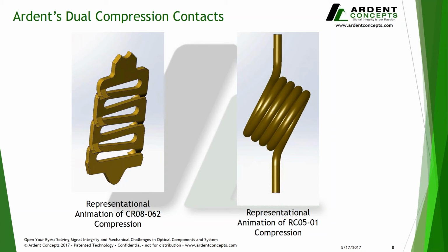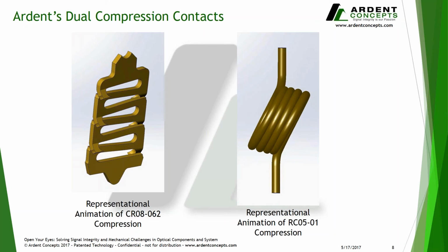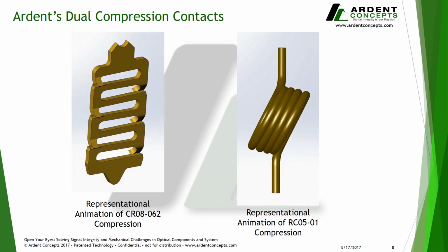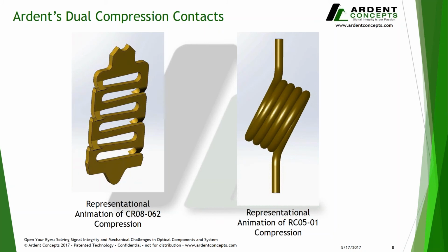You can see between the two contacts on the left, the lattices swipe against each other, and that removes oxide buildups. On the right, the coils wipe against each other, which also reduces oxide buildups. So inherently, the system is very durable and has good electrical performance over its lifetime without any degradation.